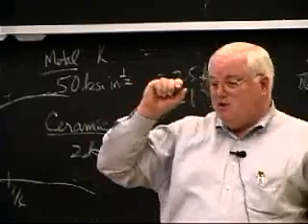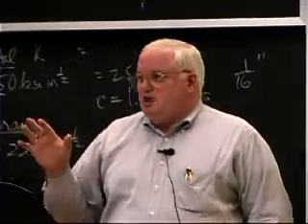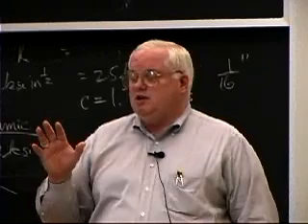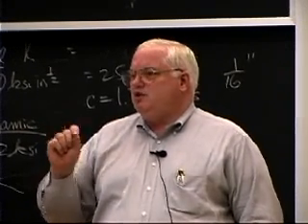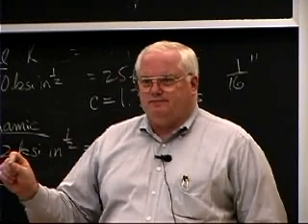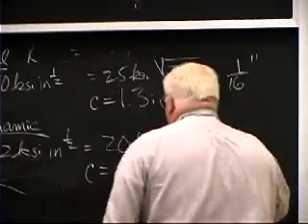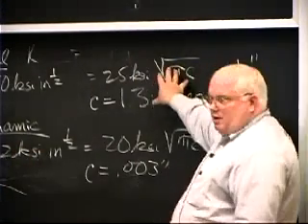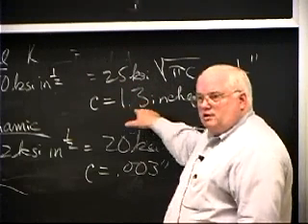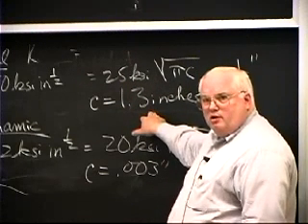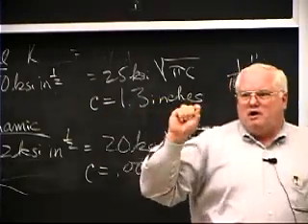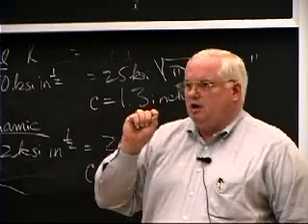Well, it should tell you that for most types of non-destructive testing, you're only doing it as a quality control tool to try to make sure they're not producing really big defects. I mean, let's face it, if I were to put in typical numbers for HY100 and stress levels, I'd still end up with critical flaw sizes on the order of a couple of inches, okay? But I'm looking for flaws that are 1/8 of an inch in size.